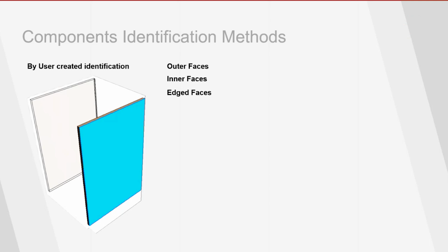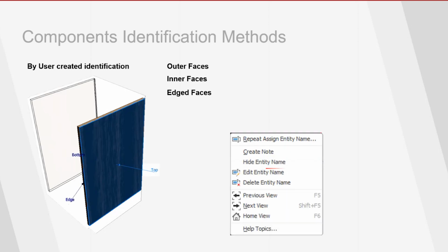It is done, I suppose, from the 2022 version. A simpler way to tag faces is giving them entity names. You know that there is such a feature in the program. It is easy to traverse the faces of the part, create sets based on the given names, and assign one or more other materials by filtering through these faces. It's again similar mechanisms.